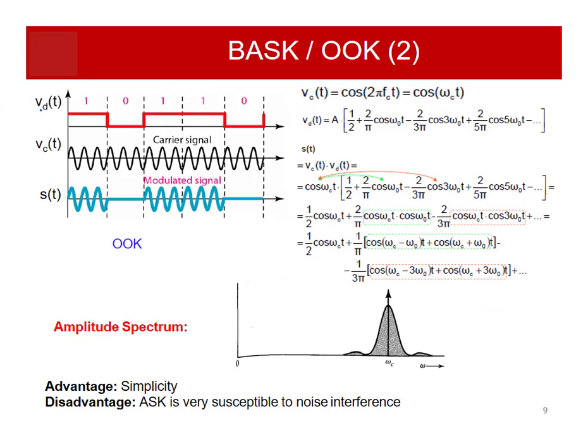Now as you can see, it is demonstrated here again. So our bit sequence is 1 0 1 1 0. This is our carrier signal, and then this is multiplied actually in the modulator circuit. So the s(t), or the modulated signal, is this one. This is the OOK type of binary amplitude shift keying. So when the input bit was 1, it has a high amplitude. When the input bit is 0, it has 0 amplitude, and so on.